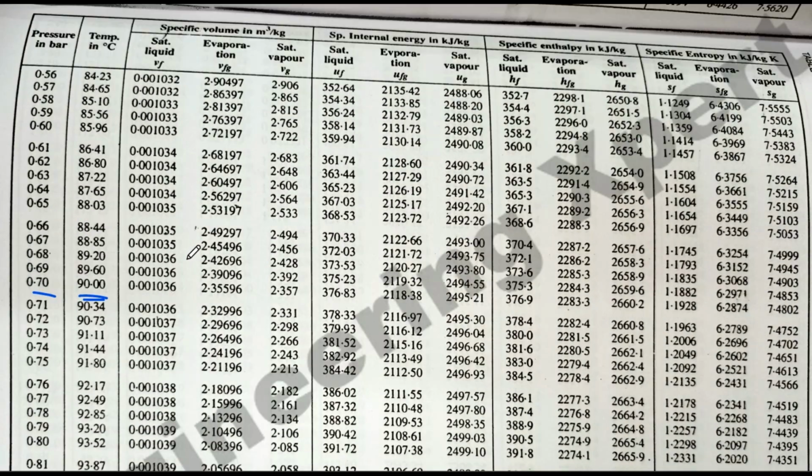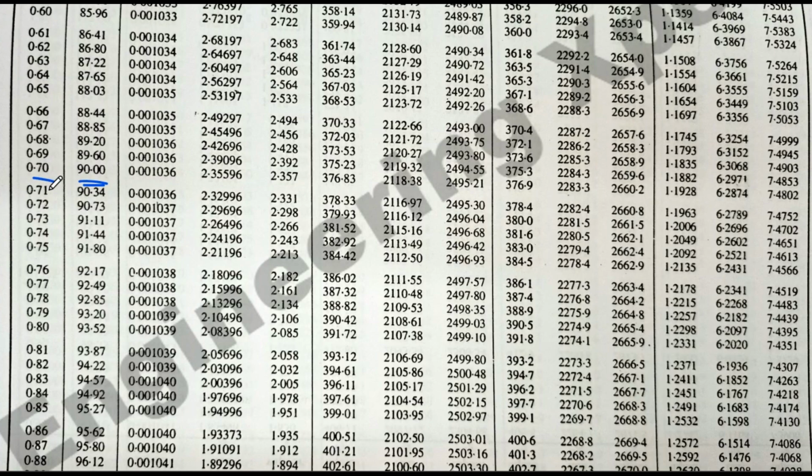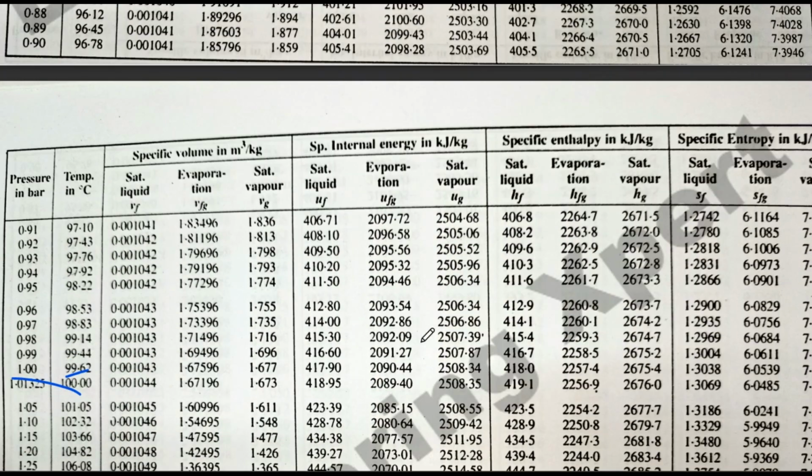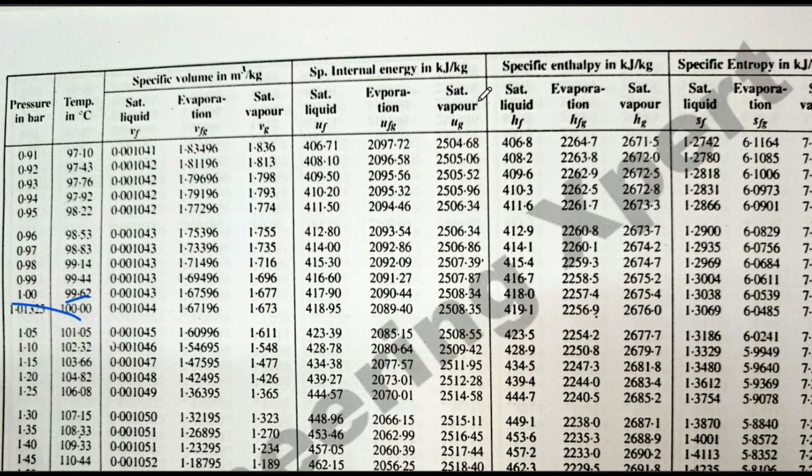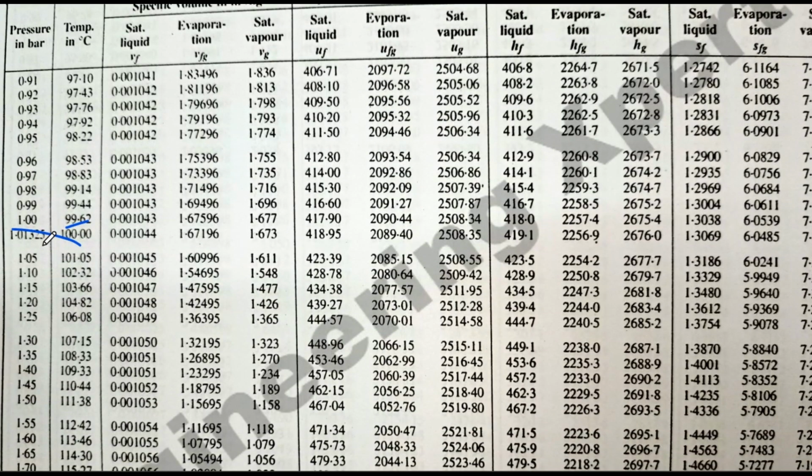And in most of the questions you will be given one of the temperature or pressure, and another is some value from the other tables, like specific volume, internal energy, specific enthalpy, or specific entropy. Suppose you get the pressure as 1 bar and a specific internal energy somewhere between 417.9 and 250.34. Then it means it is somewhere inside the dome, in the wet region. So you can find x. How can you find x?